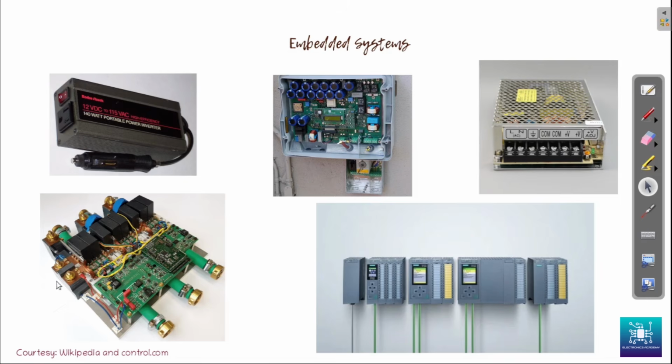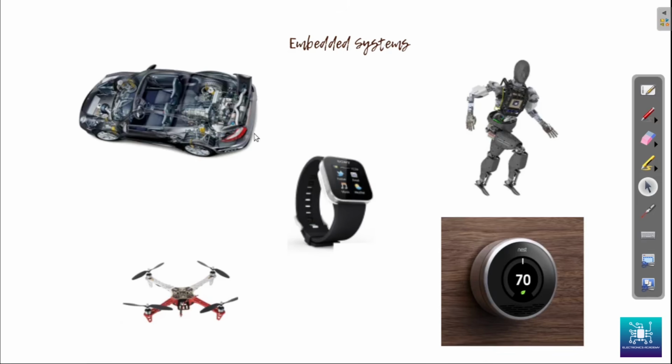For example, this traction inverter has a control component. It is a 3-phase driver, which also is a control circuitry for the motor. So this has logic for motor speed control, and it runs on a feedback loop. It might have multiple loops, and it might follow the principles of control systems. Same applies to even SMPS, PLC, solar inverters, anything that you see. Where control systems is not used to that extent, maybe an embedded watch or an MP3 player or a handheld